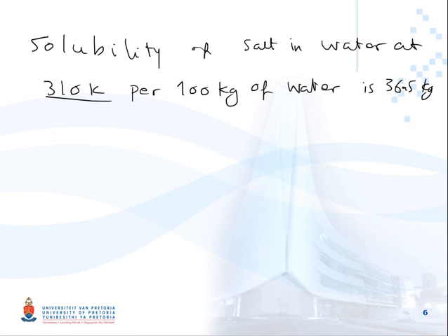How are we going to calculate it? Basically, let's say we want to calculate some kind of boundary condition in terms of a specified concentration boundary condition. How are we going to do it? In this case, the mass fraction of salt on the liquid side. If you remember, we said that those specified concentration boundary conditions have two sides.